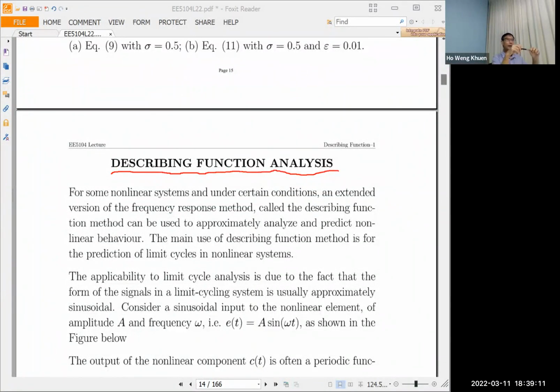Depending on your application, there are some problems that are better solved with frequency domain analysis. All electrical engineers have to learn frequency domain analysis. A typical problem that has to be solved using frequency would be an amplifier. We build an amplifier or headphone or whatever and say the amplifier must have a gain that ranges from maybe 20 hertz to 20 kilohertz, because that is the frequency range of the human ear.